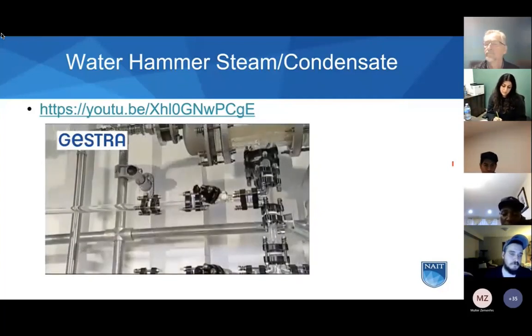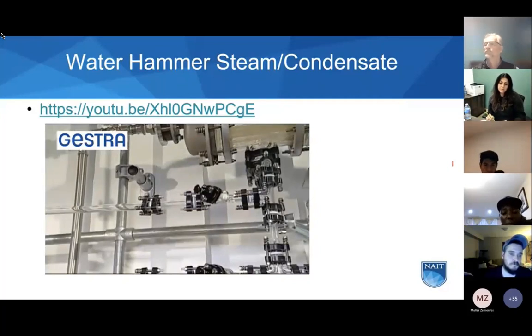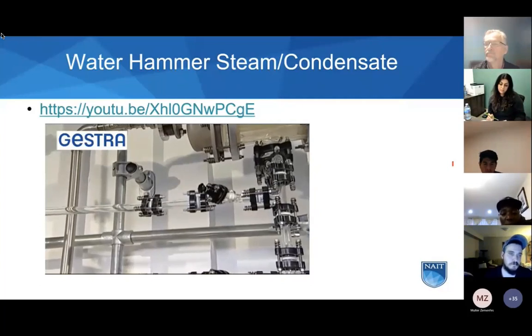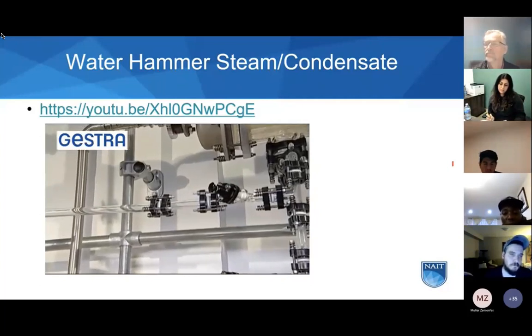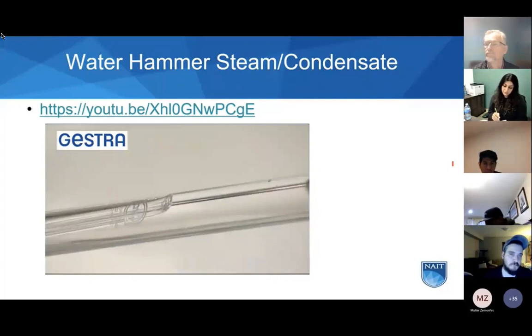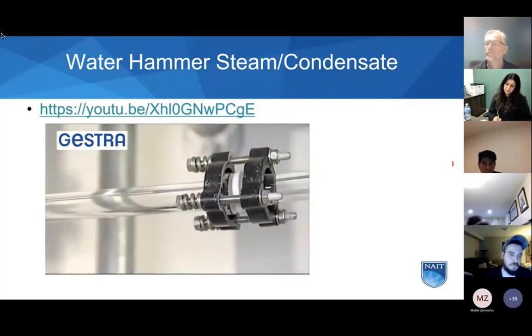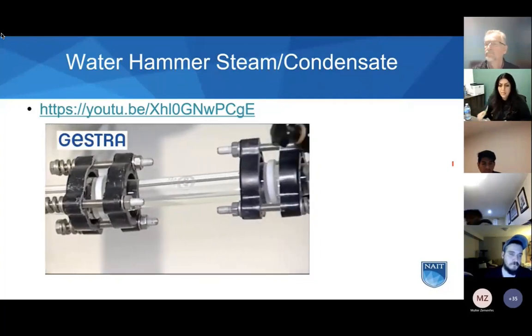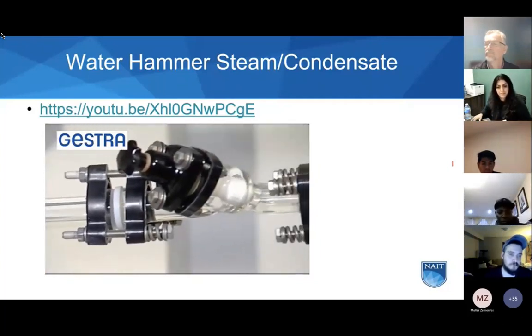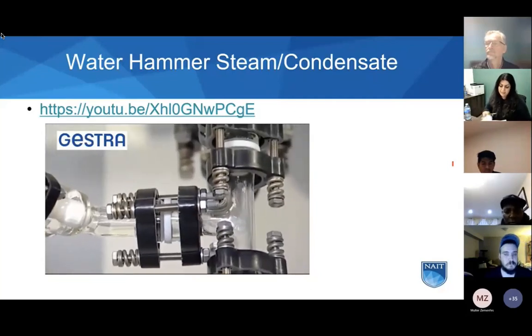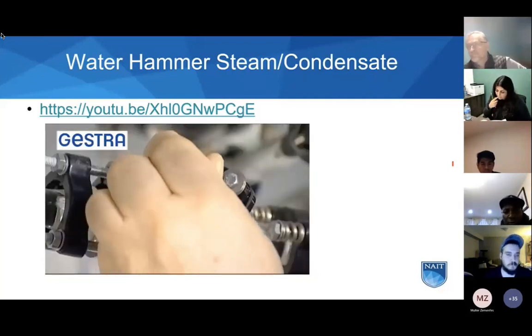In this film clip, the origin and effect of thermal pressure pulses, generally known as water hammer, will be demonstrated. For this, steam is introduced into a horizontal glass tube with a slight upward inclination, thus forming a pocket of water. The water enclosed in the tube on the left-hand side is cold, whereas steam is available on the right-hand side. This represents a typical startup situation for pipe segments with poor drainage. The steam valve is now opened slowly.